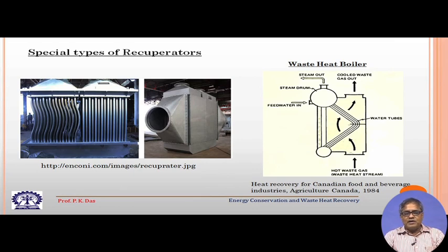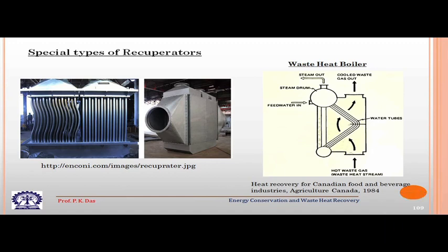So, this type of heat exchangers are called recuperators. So, all the shell and tube heat exchangers, the example we have picked up, the plate type heat exchanger, the example I have shown, or the plate fin heat exchanger, these are all recuperators. There could be another kind of heat exchanger which just now we have discussed, that is the regenerator. So, the regenerators are heat exchangers where there is a storage medium, heat transfer is from the hot fluid to the cold fluid via a storage medium.